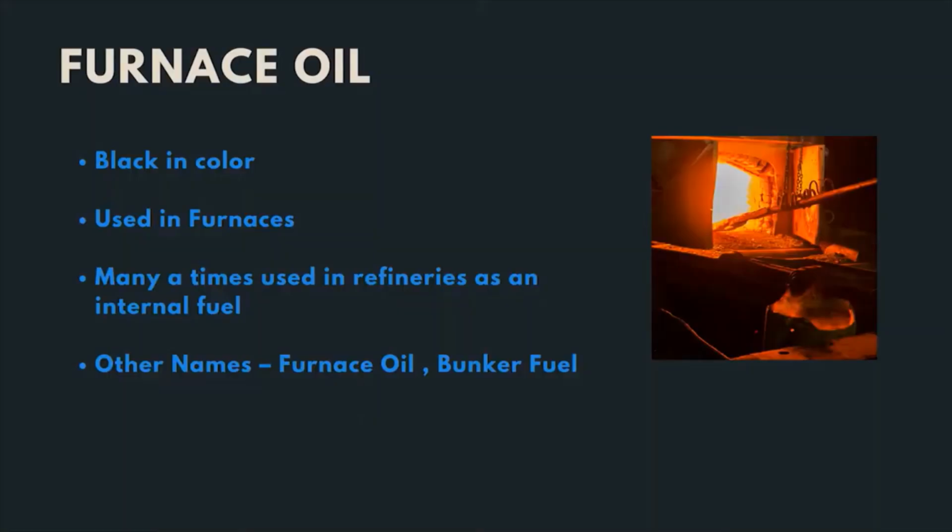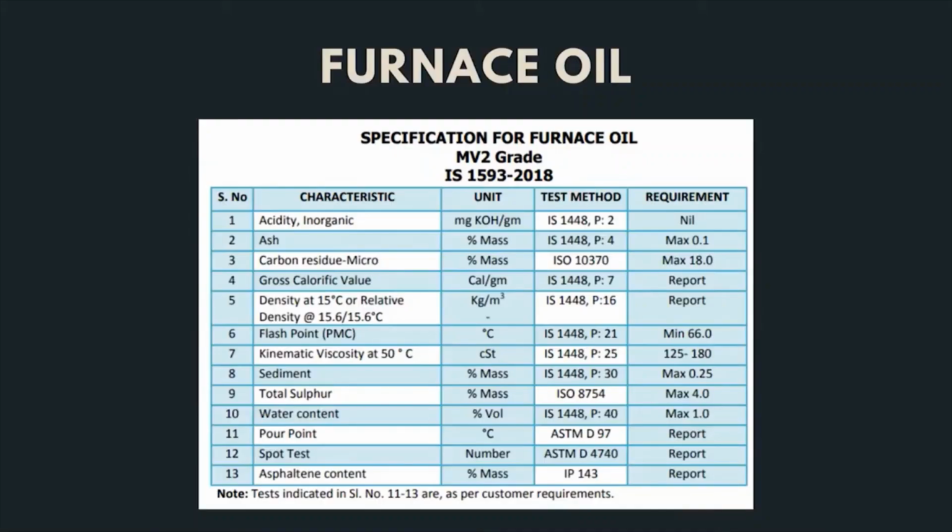The other names for furnace oil are bunker fuel and fuel oil. Here, the important specification for furnace oil would be the kinematic viscosity. If the viscosity is very high, then it is very difficult to pump it from one place to another, or even within the plant or inside the burner.